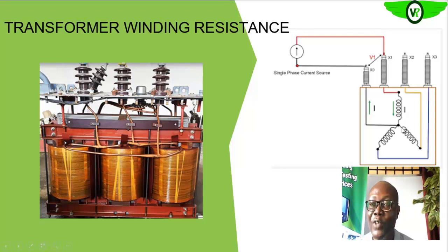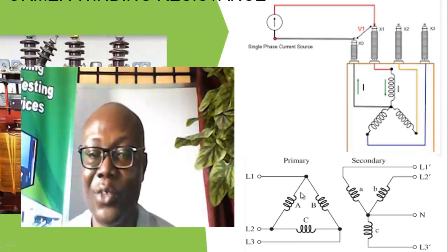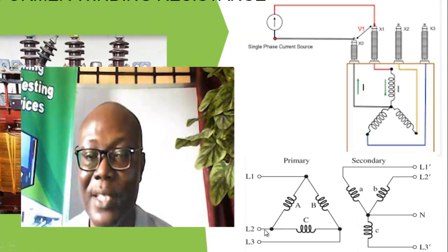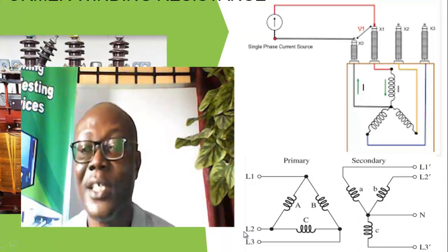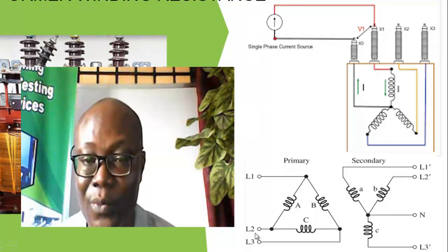So if you are looking at the high voltage side, you only have these 3 connections. This start point will not be connected out. If it is star connected, if it is delta connected, the same thing too. You only have 3 connections. So these are the various connections on the primary side. Like we explained, this too also is true for the electric motors case.